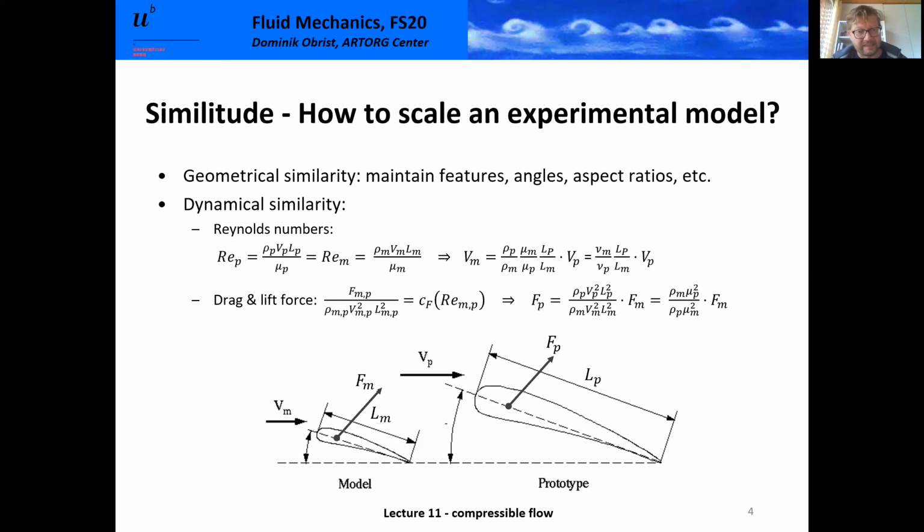That's exactly what it says here on this line with these formulas. Let me just try to point that out. Right, so we have here the Reynolds number P, P for problem. This is like our commercial airliner. It has a density that will be the air in which the airliner flies, the velocity of the airliner, the length scale, let's say the wingspan or the length of the fuselage, and the dynamic viscosity of the air.